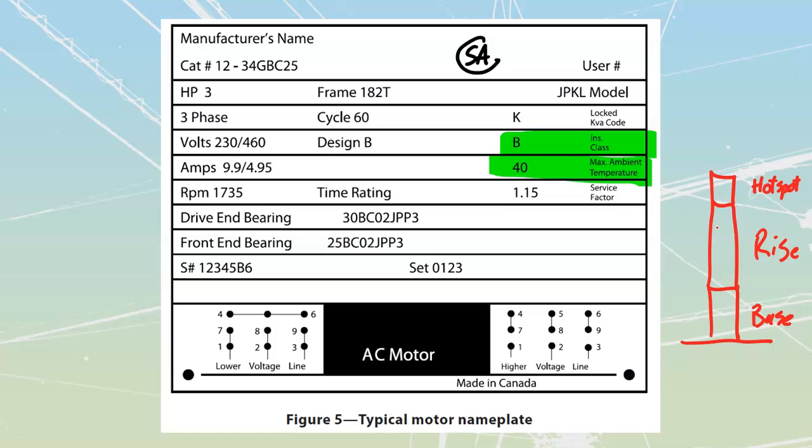And what this tells us is basically how hot this motor is going to get during operation as well. We're going to have to use these later on when we are trying to size all of our motors, for which temperature I am going to use for my conductors coming in. Because this insulation class tells me what my internal temp could possibly be, okay? Internal temp. Now you've got to think that if that's my internal temp off of this class B, that internal temperature is then going to get transmitted to the outside, because I've got copper conductors. Copper carries heat very, very well.